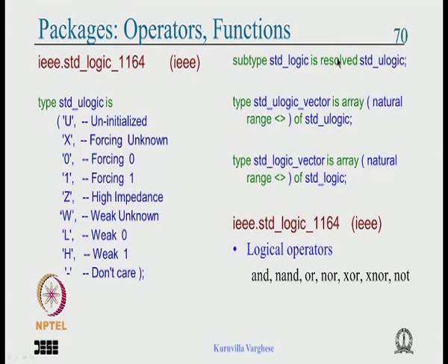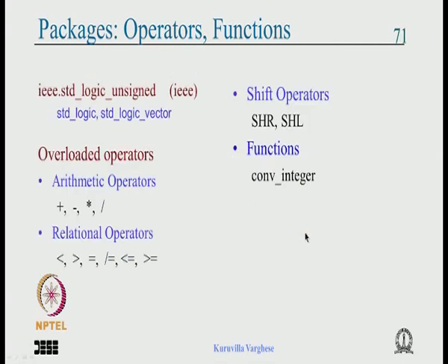We will see that as we go along in the VHDL. We have std_ulogic_vector defined as an unconstrained array, and std_logic_vector which is defined as an unconstrained array of std_logic. In this std_logic_1164 package, all the logical operators like AND, NAND, OR, NOR, XOR, XNOR and NOT are overloaded for std_logic and std_logic_vector. So if you want to use logical operators with std_logic, then use this particular library. And also it has